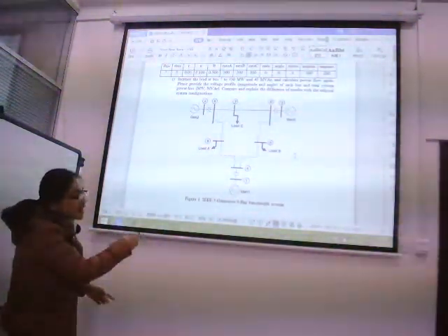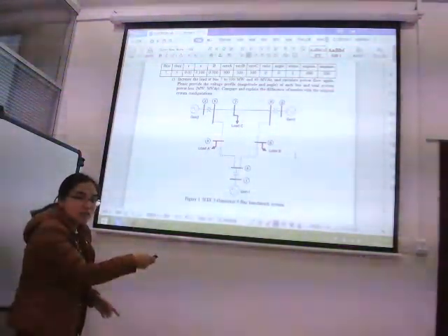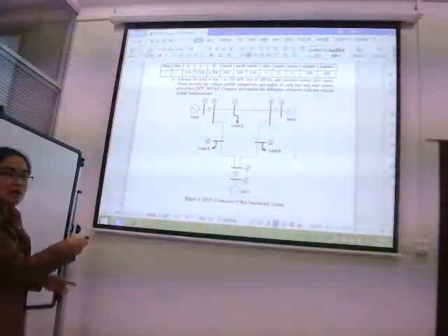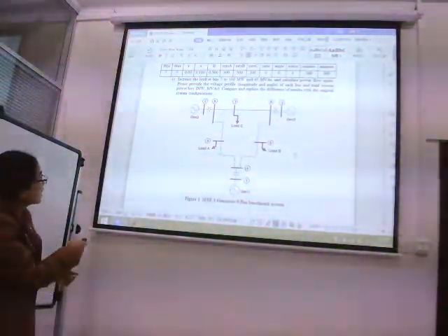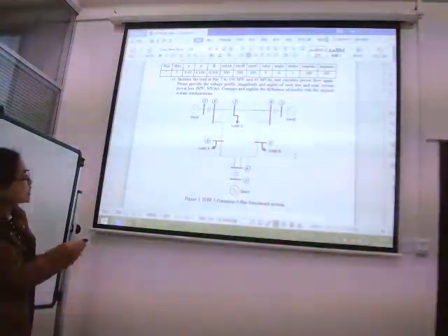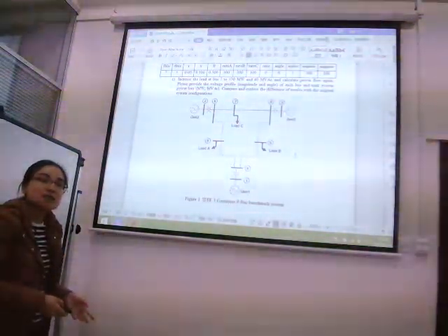If we add 1 line here, then there is power flow from bus 7 to bus 5. Then we do not have to transfer that amount of power as originally from generator 2 and generator 3. So the power loss is decreased. Is that clear?